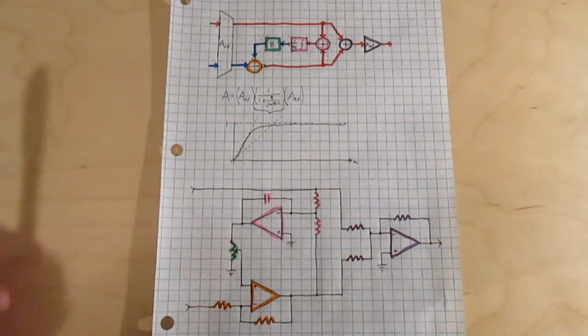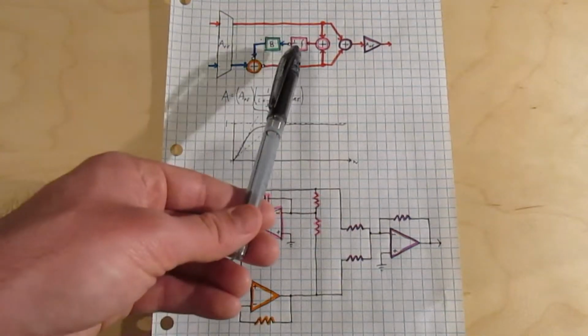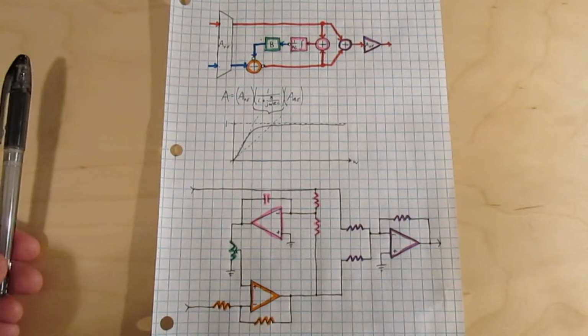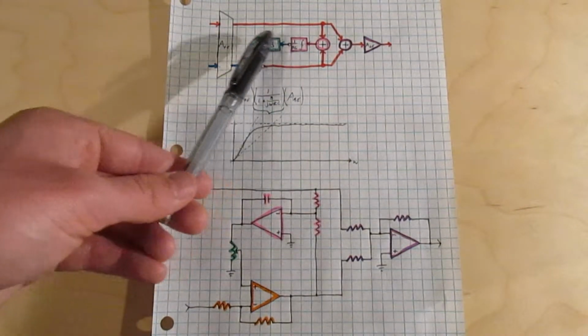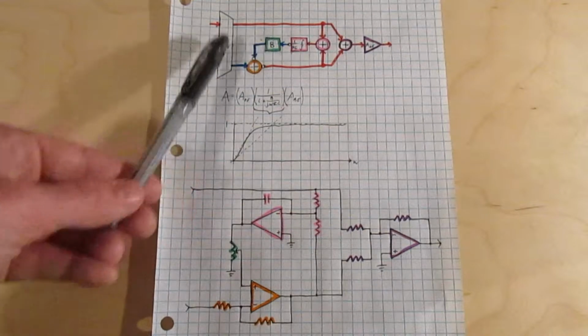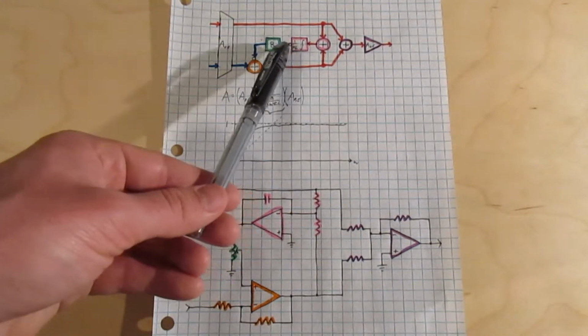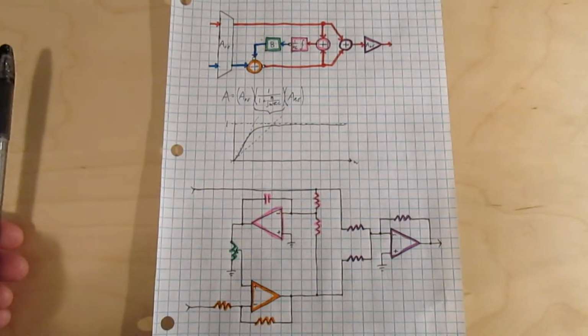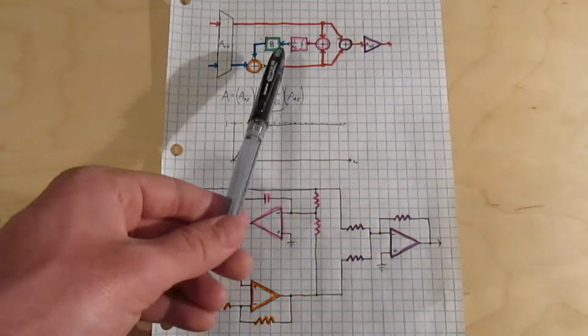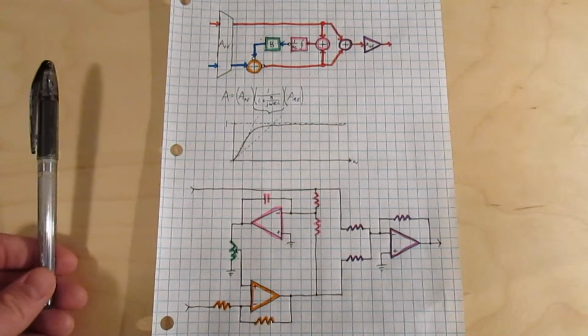So here's a circuit I came up with that would do that. I use an inverting integrator instead of Jason's non-inverting integrator. And then instead of adding it to the negative signal, I subtract it from the negative signal and it has the same effect. But this time, because it doesn't have that 1+ term in it, it also doesn't reduce the gain. And I reduced the corner frequency by adding an attenuator in the feedback path.